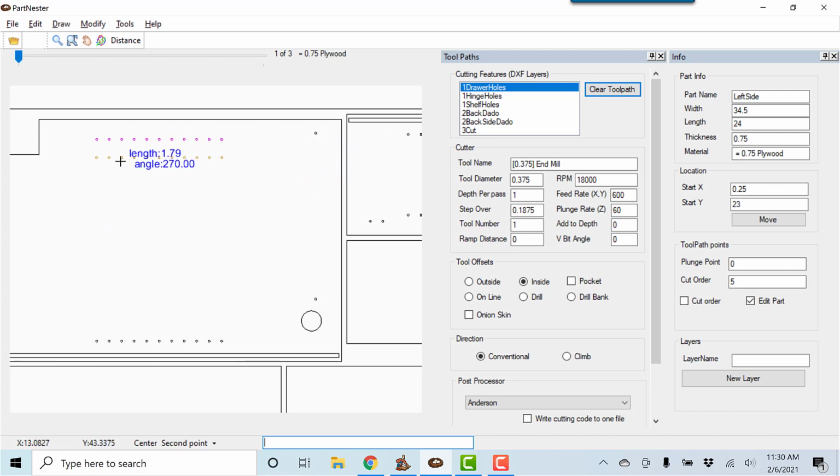That is the ortho. And if we want to move it down a specific distance from its current location, just using at, say 4 or 5 inches in the direction of 270 degrees, which is in the down direction, hitting enter, that just moved it down from where the base point was selected down 5 inches, or moved it 5 inches in the 270 degree direction.